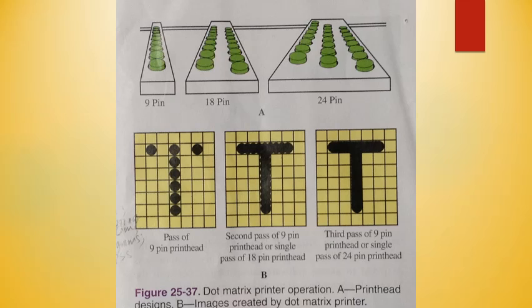When the solenoid is energized, the print pin moves forward, rapidly striking the ink ribbon. Each energized solenoid causes the individual print rod to strike the ribbon, leaving a dot of ink on the paper to form a letter, such as the letter A. A series of electrical pulses are sent to the print head. The pulses are coded in a sequence that forms the letter A. The letter is printed as the entire print head moves horizontally across the paper. The common print head styles are 9-pin and 24-pin. Dot matrix printers are noisy and limited today for use with text applications, not for graphics. When graphics with fine detail are desired, other printers such as inkjet or laser are used.